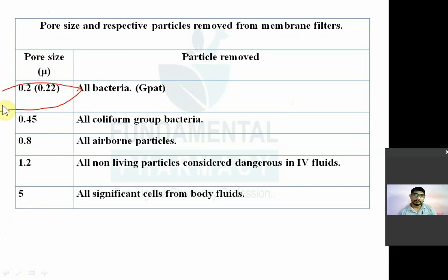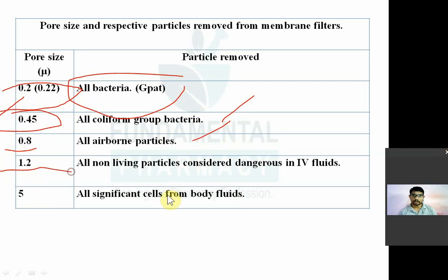Plates are arranged in one unit, so that is known as a plate and frame filter. In this way, and there is an outlet also, the frame has an outlet. These are arranged in a series, parallelly. Because of this arrangement the surface area is increased and it can be utilized. It can also be utilized for filtration of sterile products as long as all the utilities are enclosed and it can be sterilized. Sterilize this first, and after that you can use it for sterile filtration. This is a plate and frame filter.